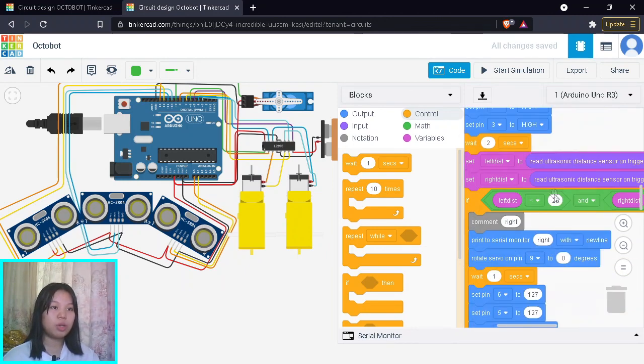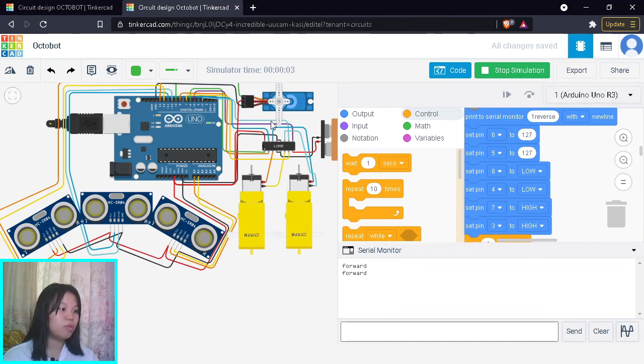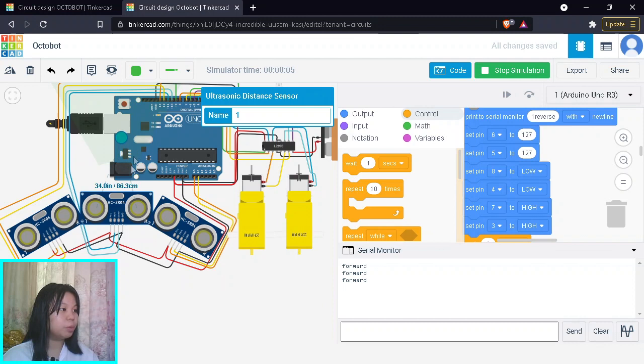So this is our code. I'm going to start the simulation and open up the serial monitor. You see the initial state: it turns to a center position, so the steering is looking forward. Now this is scenario 1: there is no obstacle in front, it's more than 20, so it's moving forward with positive RPM at maximum speed, 31 RPM now.